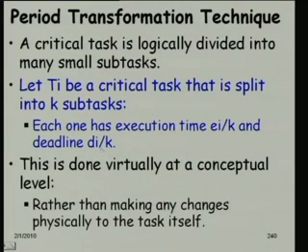So, if we can use that in our schedulability analysis, possibly it will become more schedulable, right. For the k minus 1 tasks, if the deadline is missed by a small factor, it is not a problem. But if the deadline of the last subtask is missed, then the task will fail, right, just remember that.